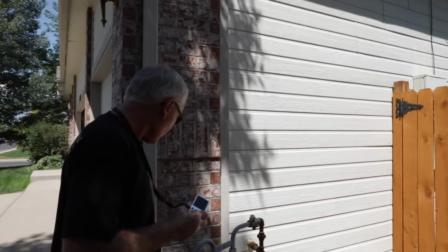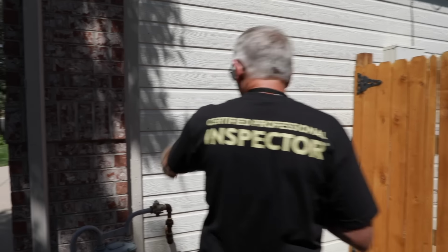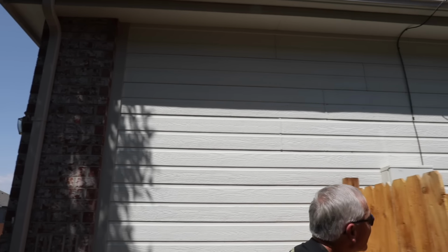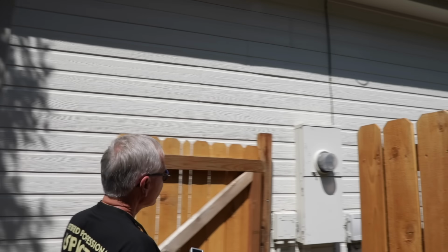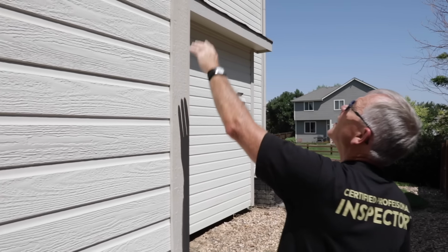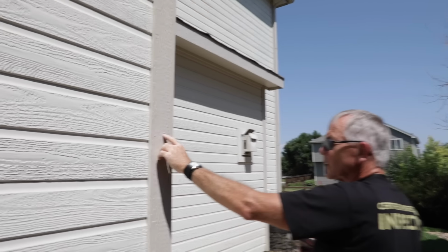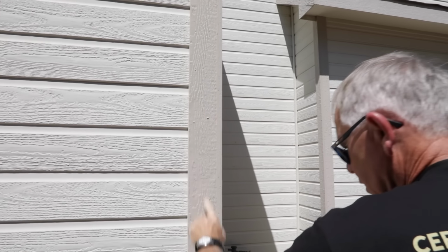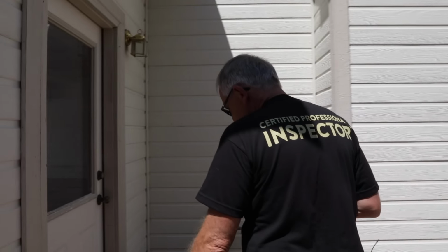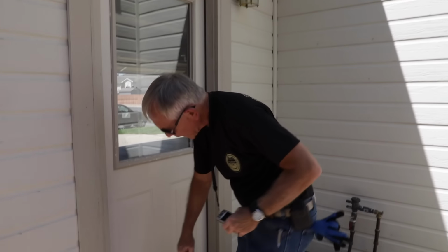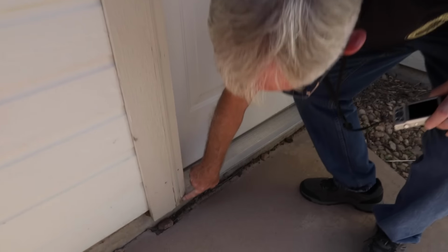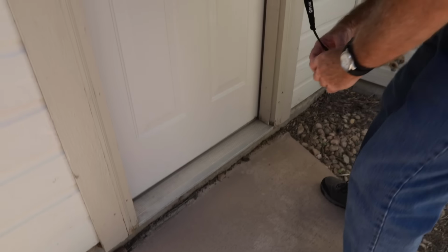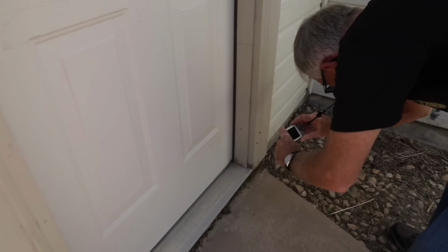All right, let's go ahead and move on to the next side of the house. We'll check our corner trim here. The trim next to the soffit. All looks good. Got a little bit of an overdriven nail here. There's really no room for any caulking, so I'm just going to leave that. And we got a little bit of missing paint here at the bottom of the trim. Probably just put that in as recommended maintenance.